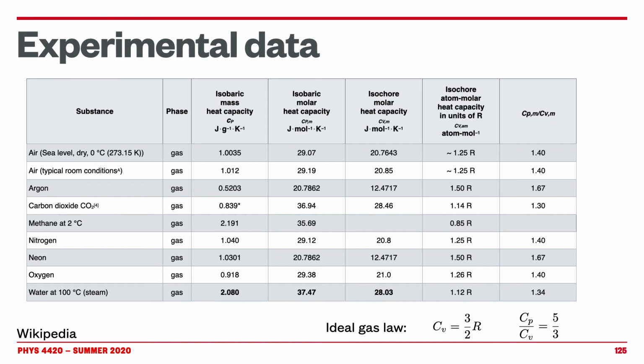What's also interesting is to calculate CP over CV. That's in the last column, and again, we would expect 1.667, right? 1.66667 as for an ideal gas. And we see that again, those values are not exact, but you would not expect that. But they are pretty good, actually, even for air, which is the gas that we deal with the most of the time. So that means that the ideal gas law is actually not bad at all to use for these things. So that's good.